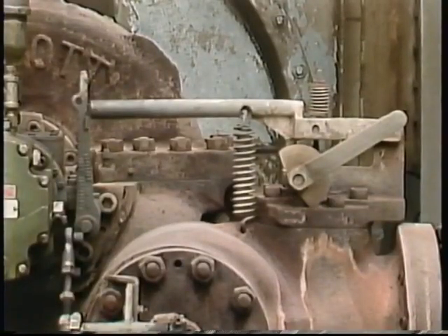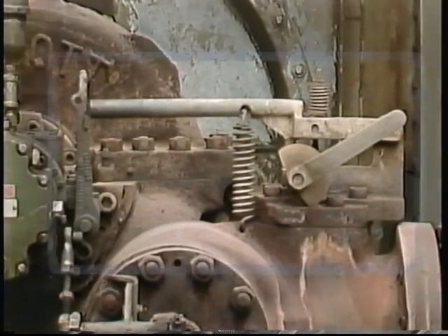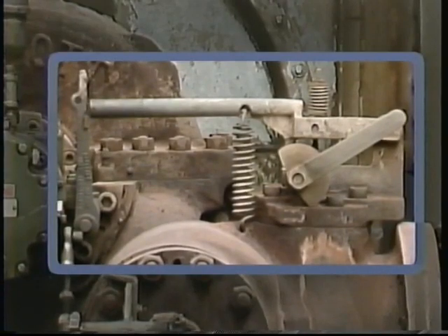The first of these protective devices that we'll talk about is an overspeed trip mechanism. The overspeed trip mechanism is used to protect the turbine from being damaged in case the turbine speeds out of control of the governor. As you may imagine, a turbine that flies apart due to uncontrolled speed can be very costly to a facility. It also endangers the health and safety of the turbine operators. So it's vital that you have some way to quickly stop or trip a turbine if overspeed conditions develop.